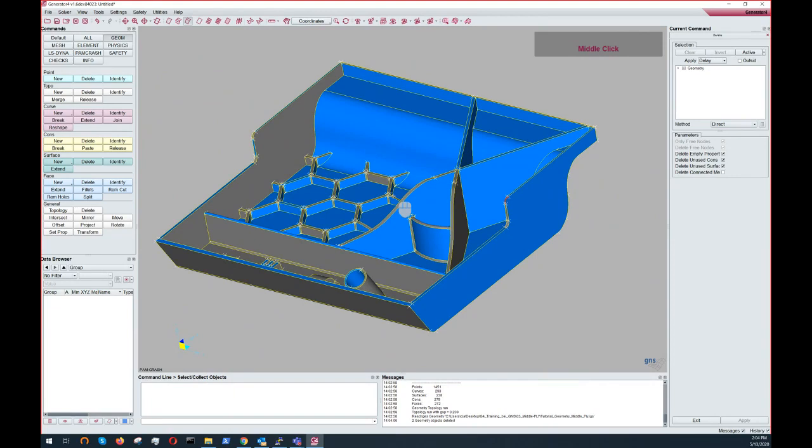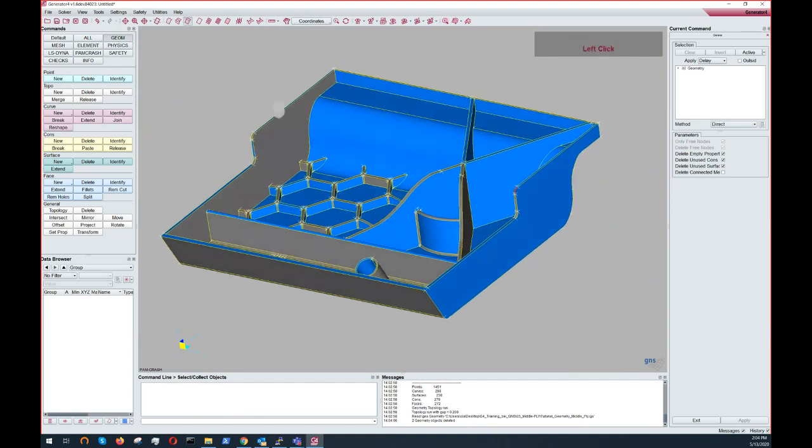Of course, if you have really problematic geometry, it will reflect on the results. So it's better to work with good, clean geometry, but it's not really necessary to have it perfect. The command we are going to use is located here under geometry, face, new, middle plane.